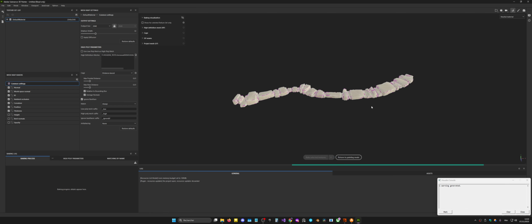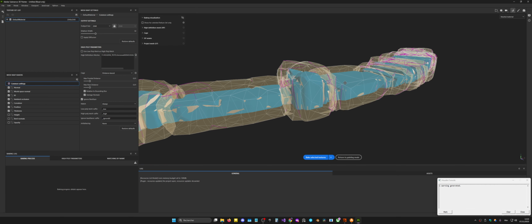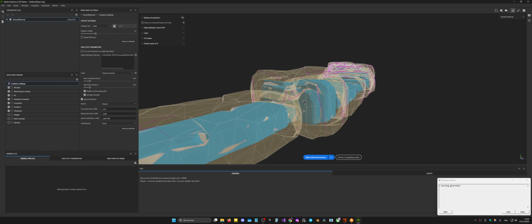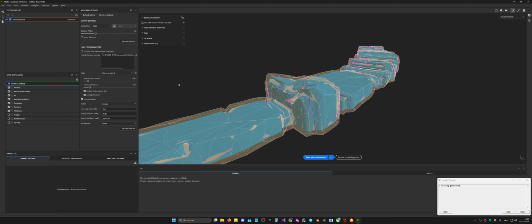Cage offset should be all the time fine-tuned because it depends on the mesh scale also. So as you can see, the cage, the limit is very, very large though. So I will go on 0.003, maybe, okay, maybe lower, maybe 2, and the same for the holes in the lower. I will use, oh sorry, a little bit of anti-alias. 2048 is the resolution. Bake.